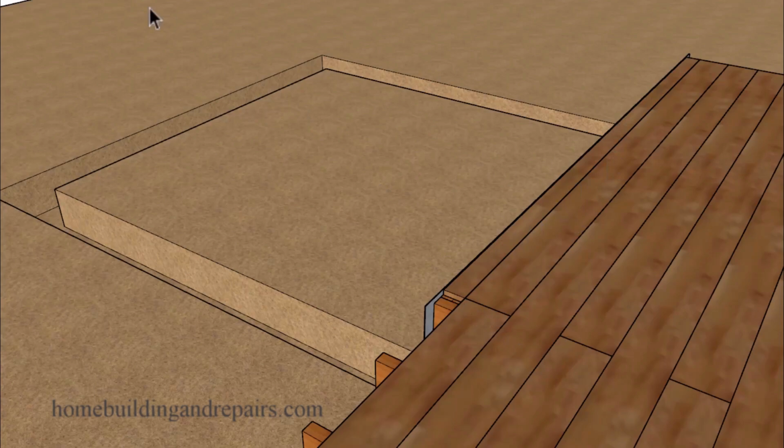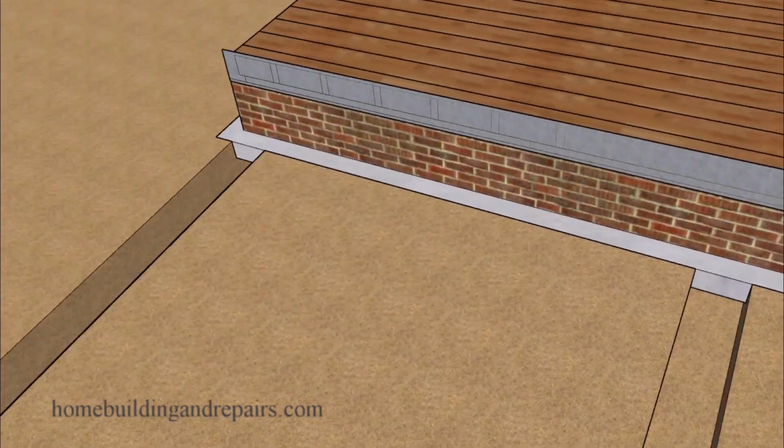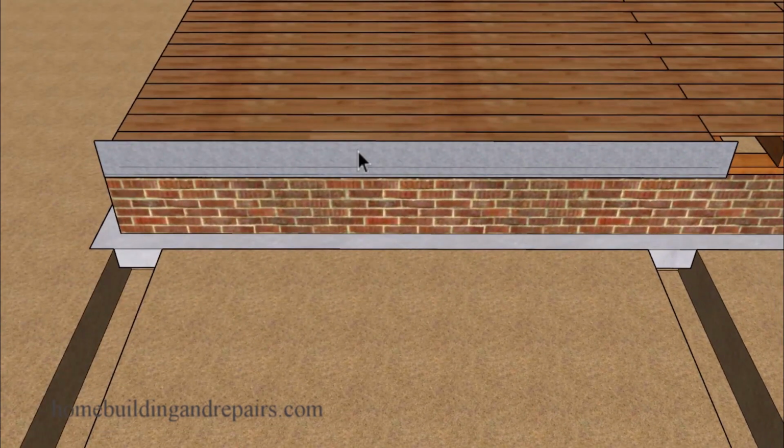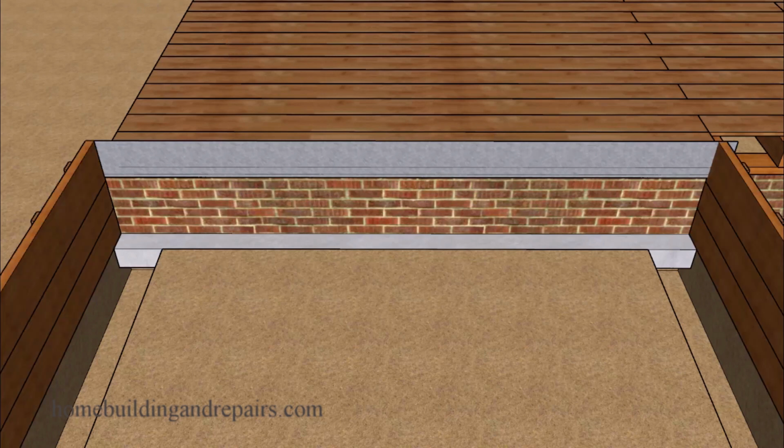And this will all depend upon what stage of the process you will need to do this. Because if you're going to leave these exterior walls to protect the interior of the existing building, which is what I usually did, then you'll simply add that furring strip later.